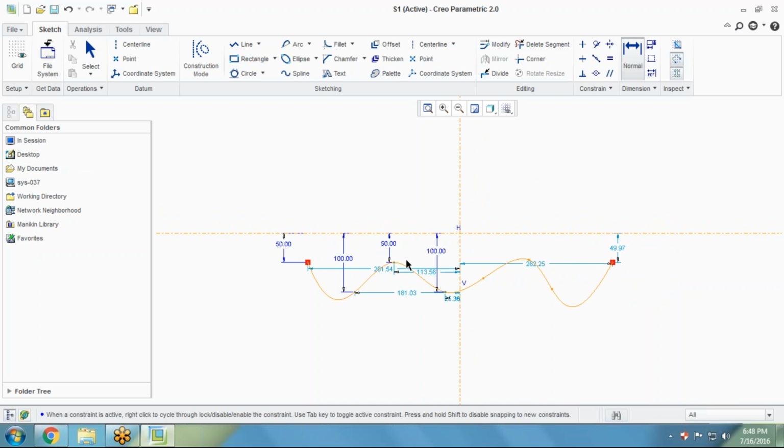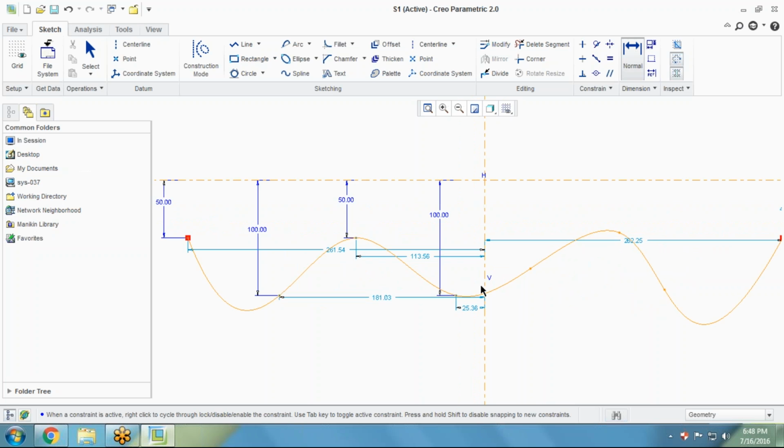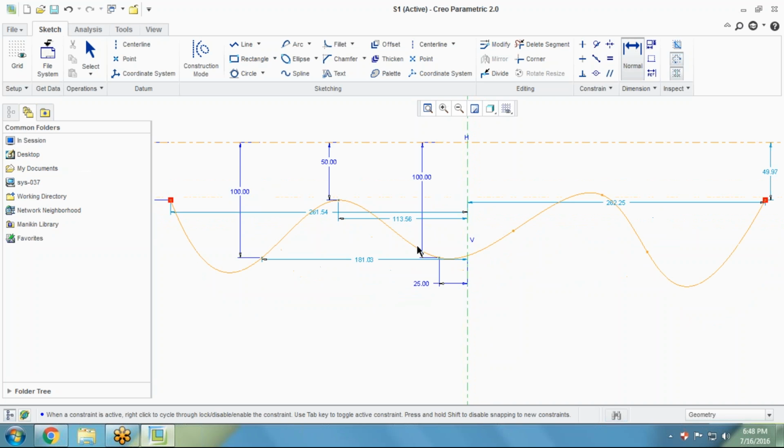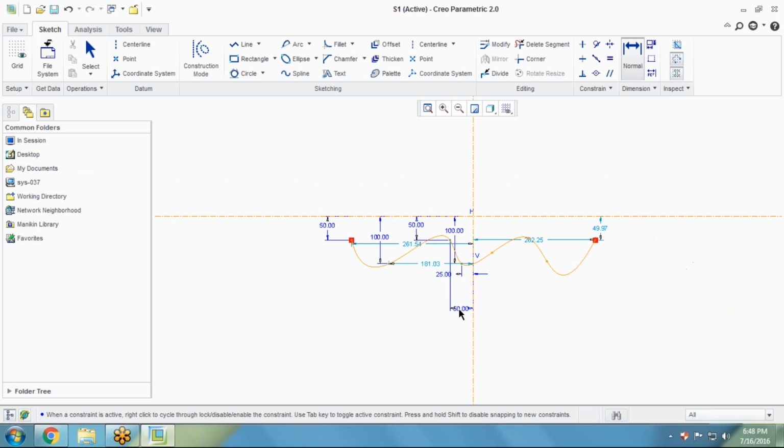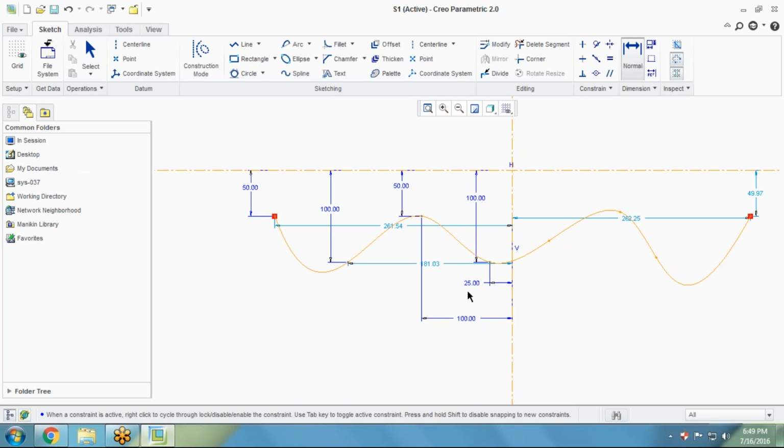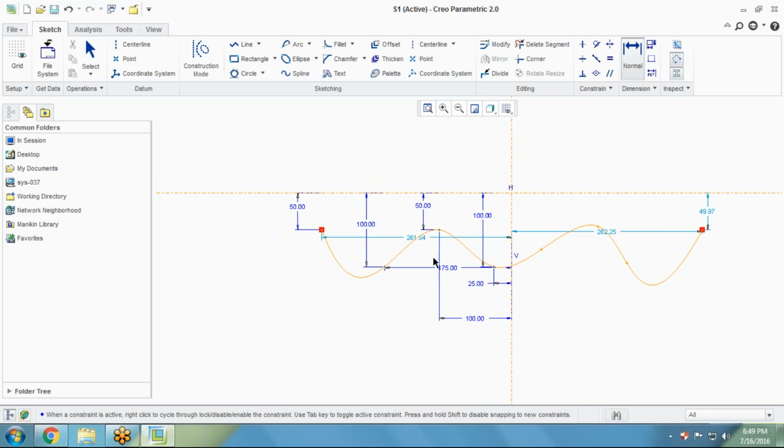These dimensions we have specified with respect to the horizontal line. Now we are working with respect to the vertical line. The size we have specified is around 25. Then the second one we are specifying is around 50. No, 50 is not looking applicable, so I'm using the value 100. So there is an increment of 75 millimeter, and the third one I'm specifying is around 175, and after that again I'm using the same increment by giving the value 250.